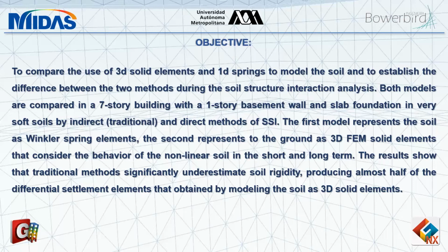And we will be looking at some of the different combinations of inputs for some of these parameters. And in the end, we will show that the results conclude that the traditional methods actually significantly underestimate the soil rigidity, and in terms of settlements produce almost half of the results as seen by the 3D solid elements. But we'll also inspect some of the structural results, like the moments and the axial forces, which are also being critically underestimated.